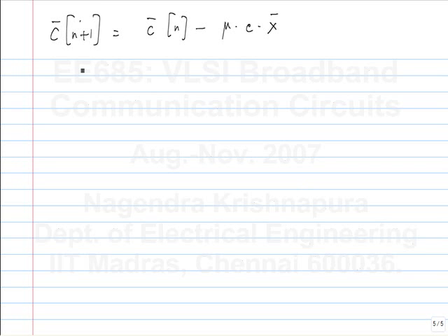So what I'm saying is, let's say the input x is coming every 1 nanosecond. At every instant you have the vector c and vector x. So between this point and this point you can update the vector c, but you don't have to do that. You can keep the same vector c up to this point, and then at this point you update it to the next value, and so on. So you update c infrequently compared to the data. The data is changing every 1 nanosecond, but you don't have to change the coefficient c every 1 nanosecond. What are the implications of doing something like that? Why would we want to do that?